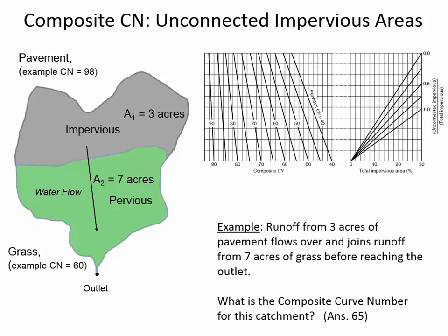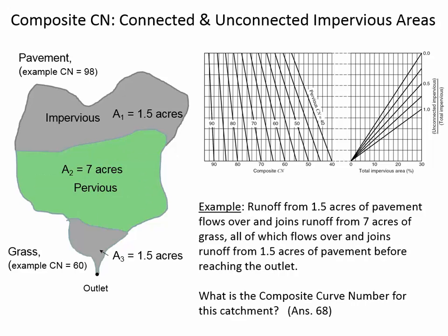But the principle is that you can have enhanced infiltration by connecting impervious to a pervious grass strip. And they're starting to do this next to roadways. They're starting to plant grass on the shoulder of the road, even when they have a concrete lined ditch that the stormwater is going to go to. Just having a grassy swale, as they call it, is a way to increase the infiltration.